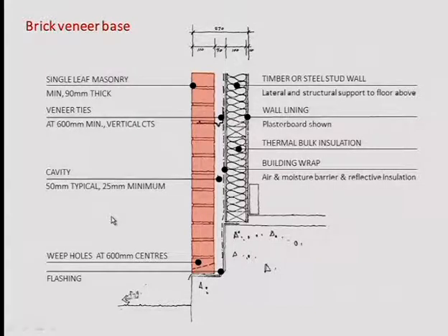Finishes, so we need to, again, either protect or have a final architectural expression. So inside there is plasterboard and lining, or there could be render or other finishes, but somehow we complete the wall placing that layer so that we don't see the insulation. We cannot touch and access the insulation. All right? So we protect it, but at the same time, it's an architectural expression because that's the way we want to see the wall.